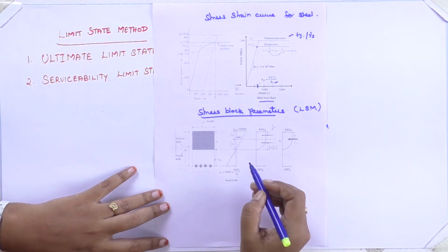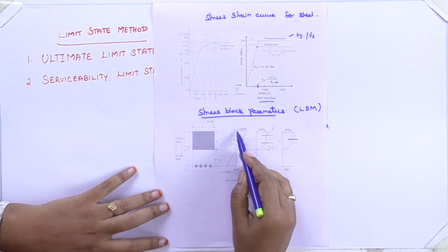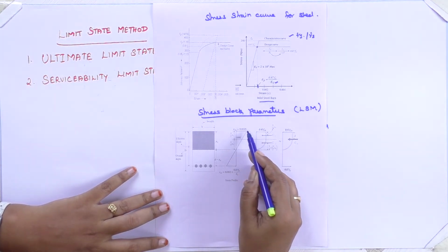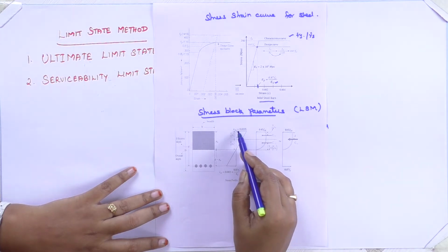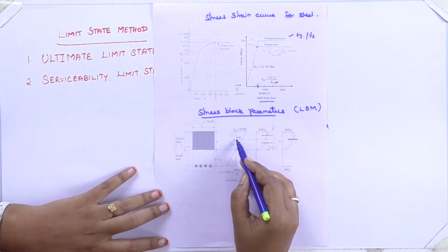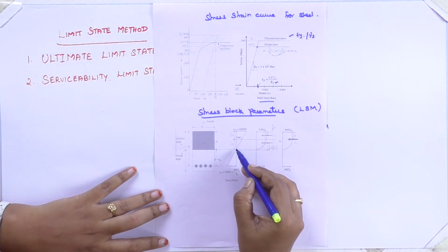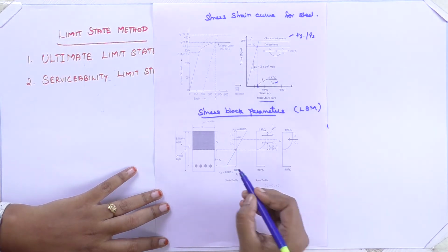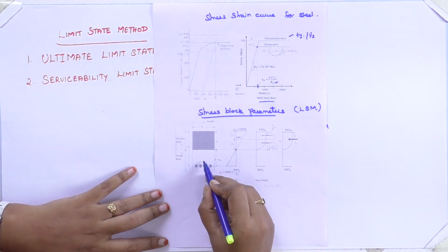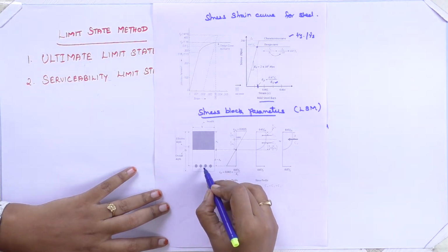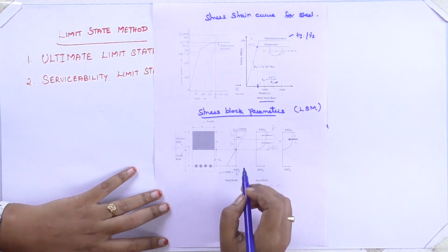When you draw a strain profile, the ultimate strain we have seen is 0.0035. Then somewhere here you will get the proof strain 0.002. Then it drops down to 0, and then changes again here. Here it is being governed by the steel. The tension part is not taken care of by the concrete. The tension part is taken care of by the steel. This concrete will be transformed to your equivalent area of steel.